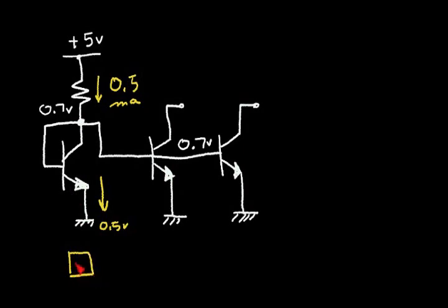So if I draw the actual physical layout of this emitter at the left, it could perhaps look like this, a perfect square, and have a certain area. Now the transistor in the middle, I want to have an emitter with twice the area. So one way is I could lay out 2 identical emitters. So the area of these 2 emitters is twice that of the area of the transistor at the left.